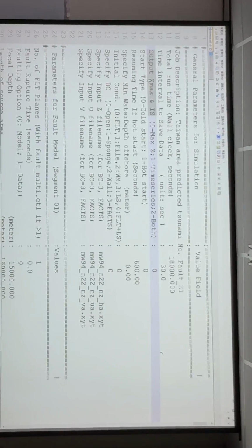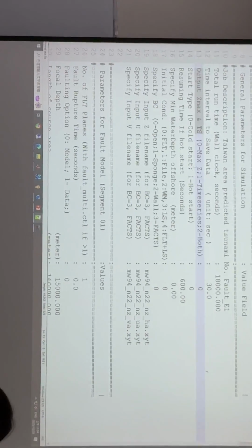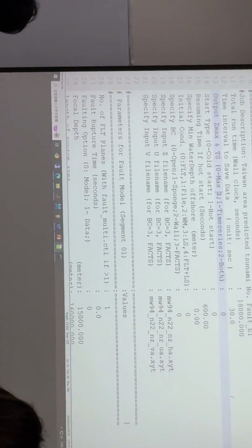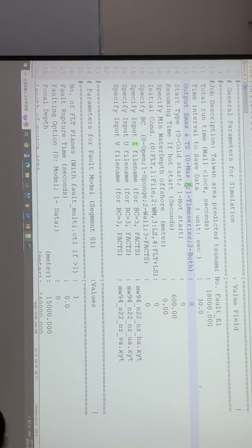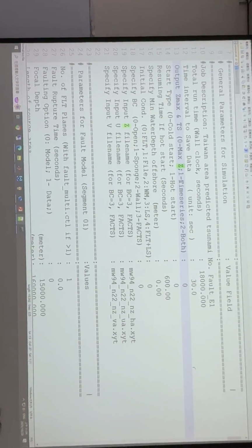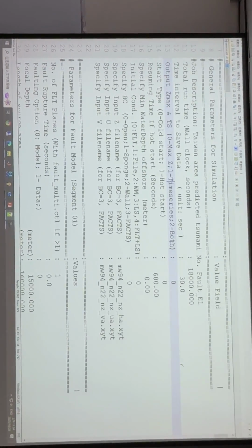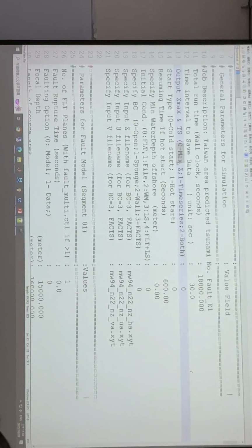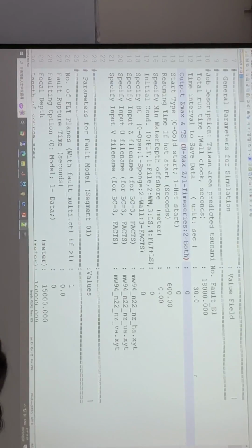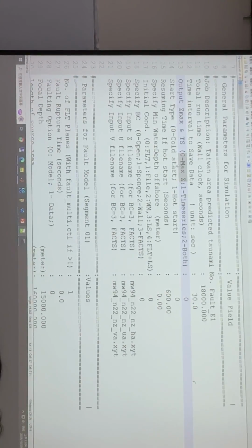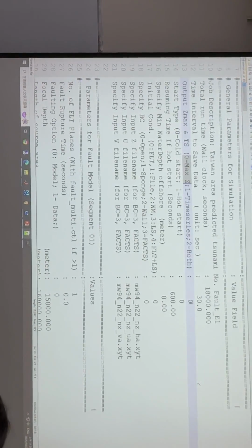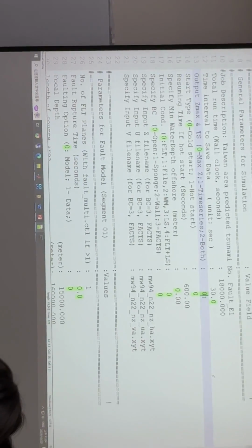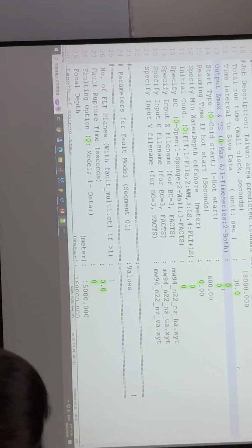And then is the output data. The output data options are the water surface elevation, Z meaning the location of the free surface, and the second is the time series, and then the surface report. So here I recommend you guys set the water surface elevation only. In this case, you need to enter 0 in this zone. Okay.